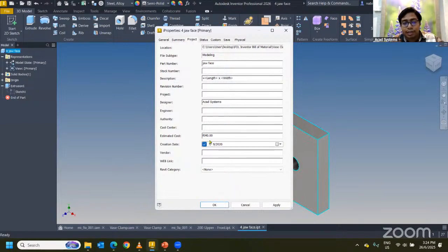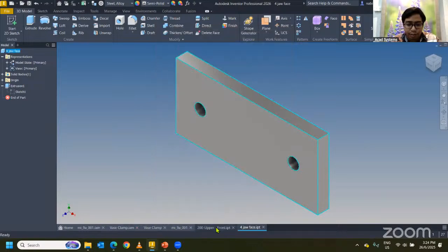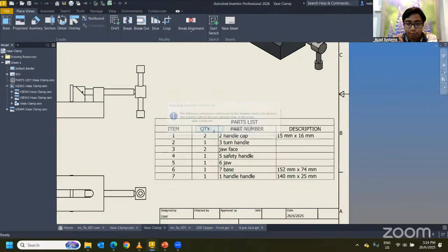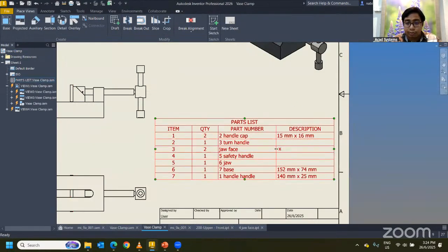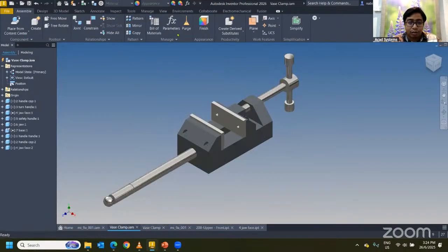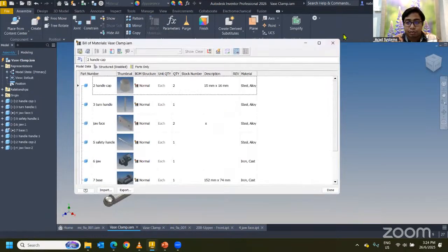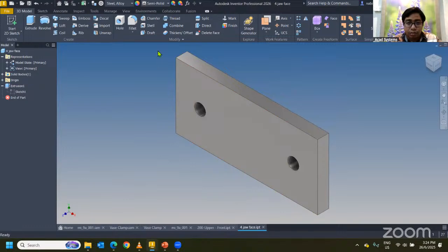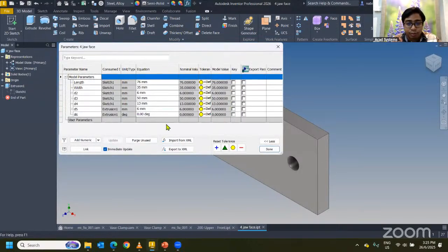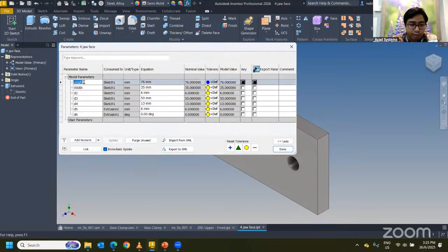Right, essentially, there is also something that you need to turn on inside of the parameter. But let's say if I just go through with this, when I click OK, and I switch back to the base clamp over here, you should be able to see now it becomes X like this. Or I can go over here and you should see that we have X only. That's not able to read. So to ensure that it is able to read from the parameter, you can find back over here. So we have length and also width.